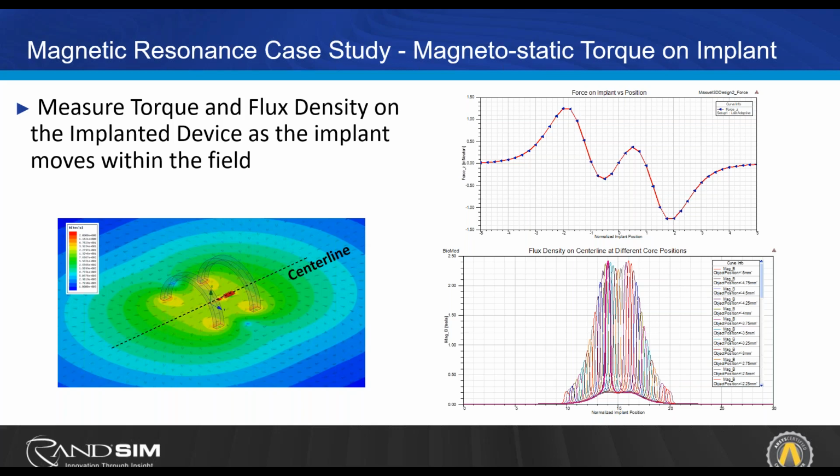And the coupling of physics, as Will showed, is very smooth. Within the electronics desktop itself, it's a little bit different than Workbench, but you can couple your CFD simulations such as IcePack. You can bring that in where it's a transition of your EM loss, quickly bringing it into IcePack, getting an IcePack simulation. You can actually couple it two ways, where it can go from IcePack to your EM solver, then back to IcePack, and you can do that as many iterations as you choose. These are all quick to input settings, and you can get that feedback quickly and readily.